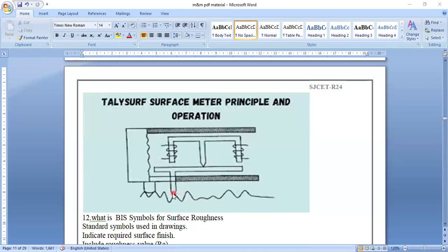So here you can see this is measuring roughness. This stylus is connected here to this one. This movement is recorded by this one. This is converting them to electrical signals, with electrodes on both sides. Electrical signals are recorded here and here. So this is totally an instrument which is continuously in touch with the surface.